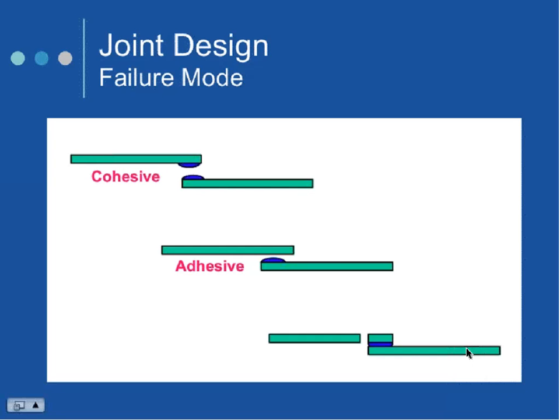What happened? Mold release, plasticizer migration, silicone oil being used somewhere else in the plant that's moved over onto my part. Or maybe somebody forgot to clean the parts the way they're supposed to be cleaned, right? As is, sometimes when you receive parts is not necessarily the best way. We always like to see an isopropyl alcohol wipe, if you can still use that in your plant, because starting with clean parts generally gives you a much better starting point and a lot more consistency over your operation.